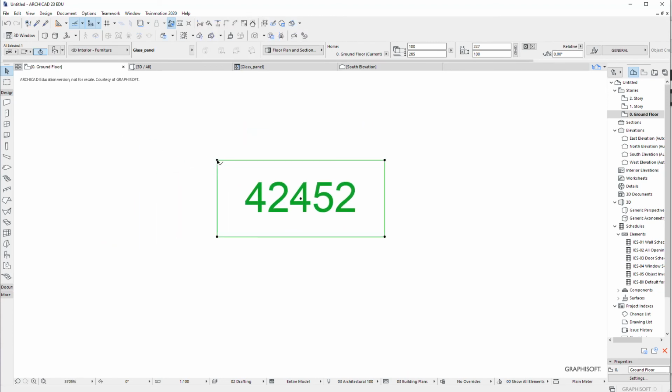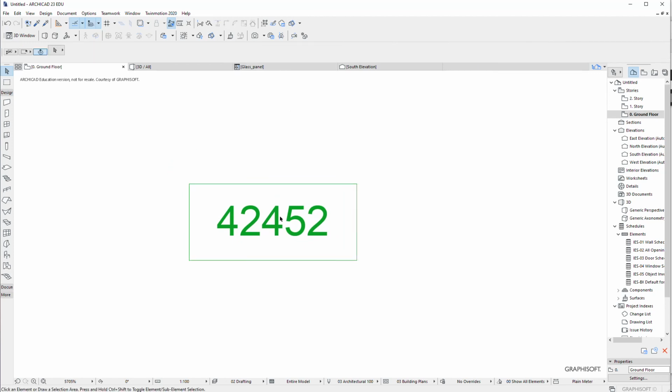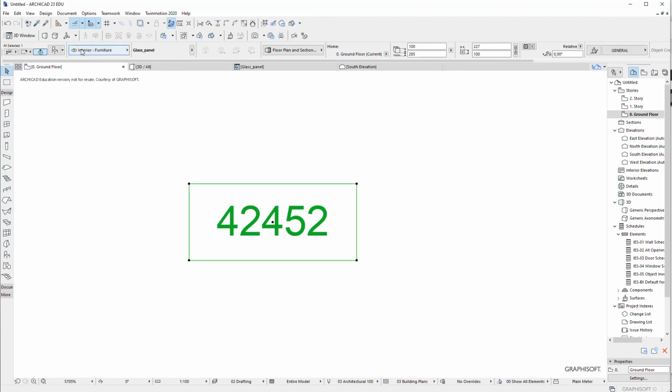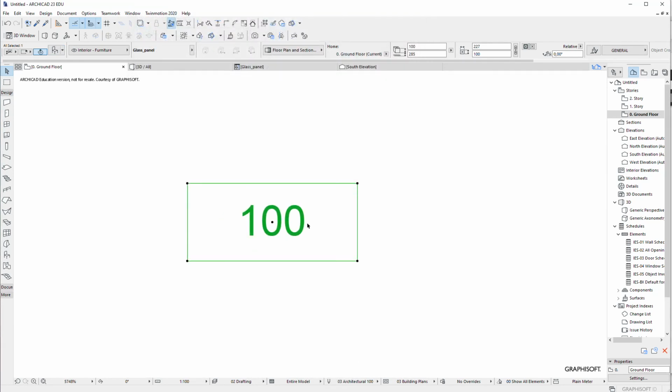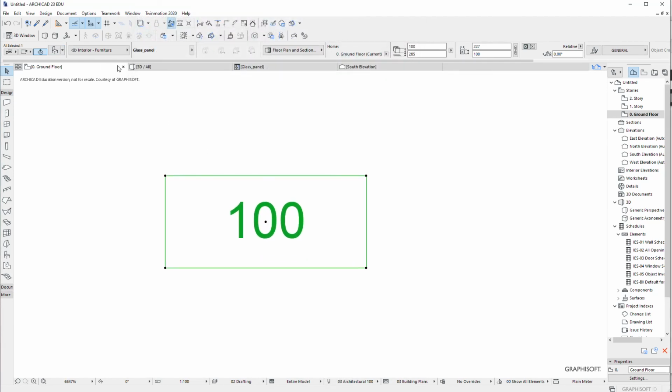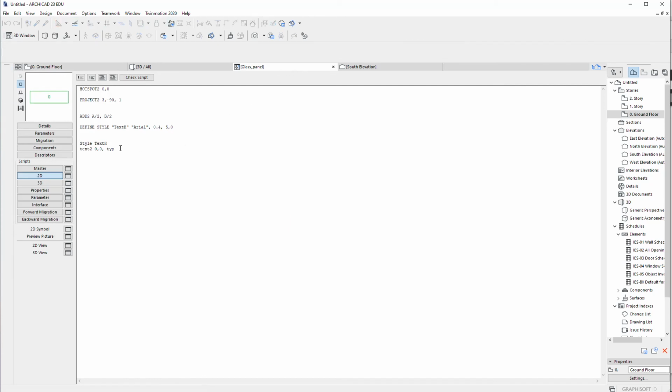I can control my objects again, and here I have my number that's coming from the parameters that I showed previously. It's nice. And from here I can edit another text. I want to tell the board that this text is the type, so I make another text, Ctrl C, Ctrl V, and I name it here like type 2 points.